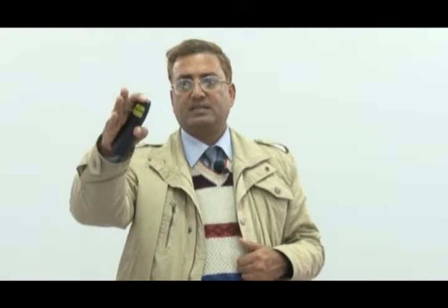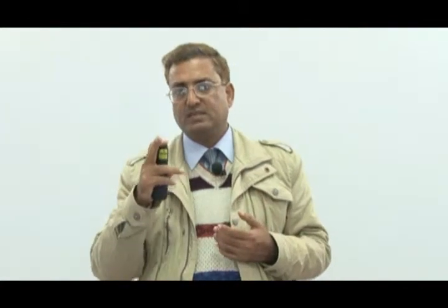And then one can impose the boundary conditions, like if this is the situation, so you have the ST and SQ, n is the normal to the given surface. If we take the 2D case here, so boundary condition can be imposed like T is T bar on ST surface and ∂T/∂n is equal to capital Q bar on the SQ surface.